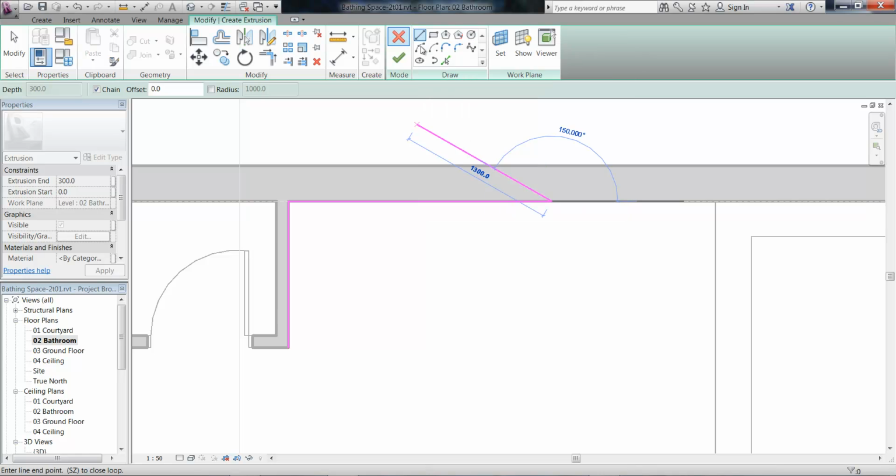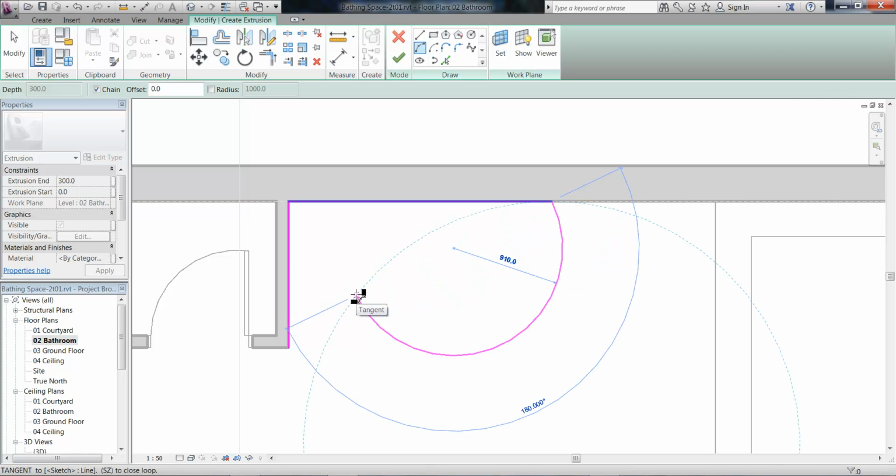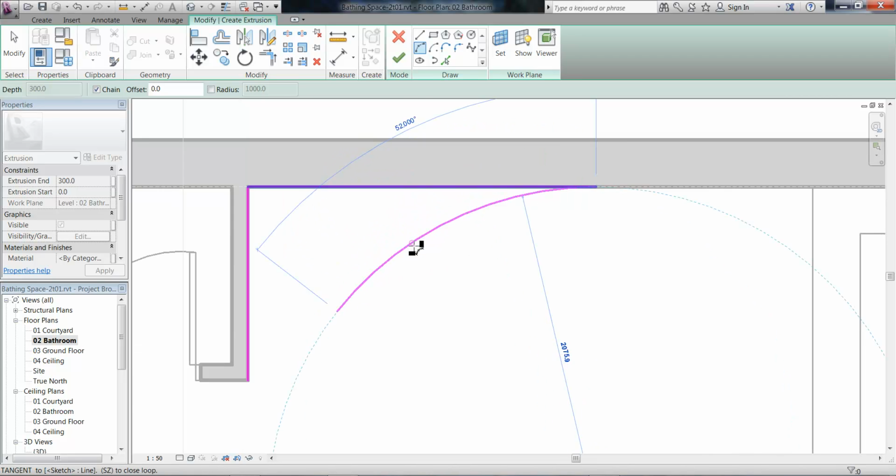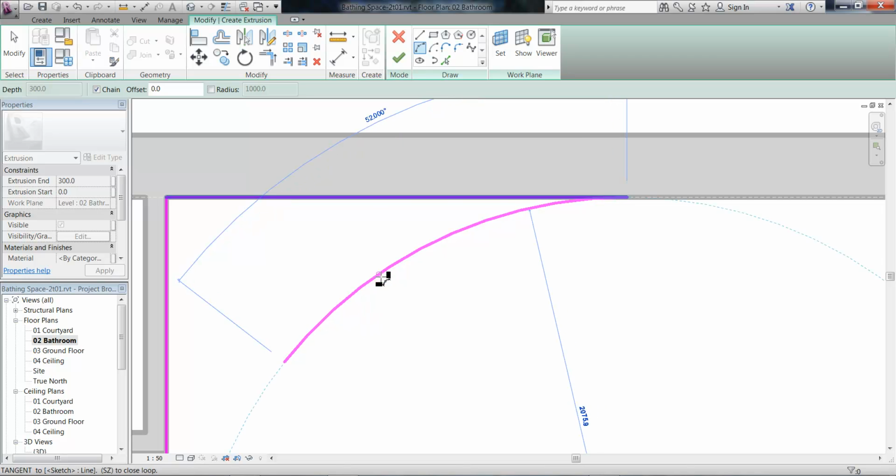Now though, I'm going to go down to the first option in the second row, which is your main arc tool. So then using it, I can give a point, actually adding space here because I want an interesting curve, so I'm going to do 2 arcs. I'm just going to click a point there for the end of my first arc, and then moving the cursor, I can give a point in the middle, which gives me the curve or the radius of that arc.